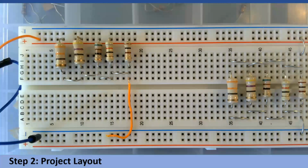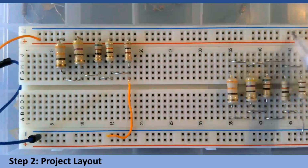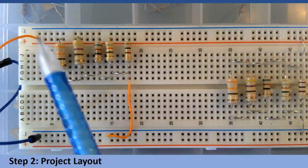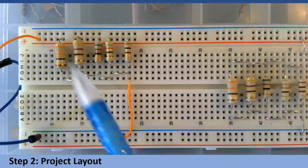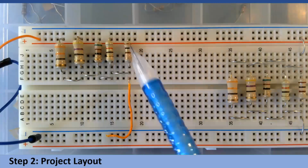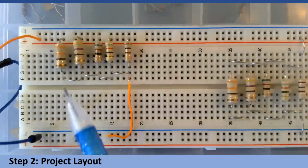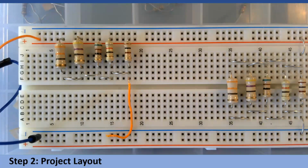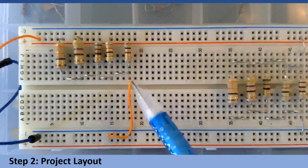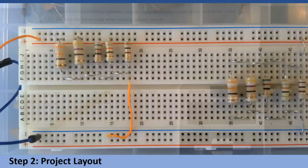An alternative approach would be to use the fact that the power rail is common. I have my supply going into my positive power rail, and then I've placed these resistors with one end into that power bus. Then I have jumpers forming another power bus on the other side of each of the resistors. From there, I take a jumper that leads to my negative and completing the circuit.